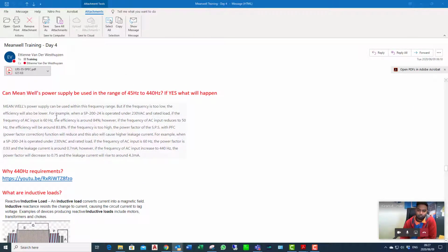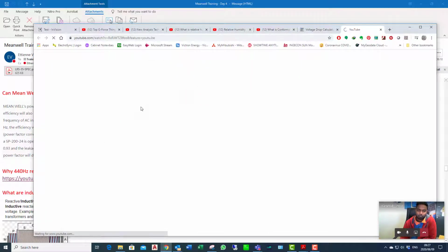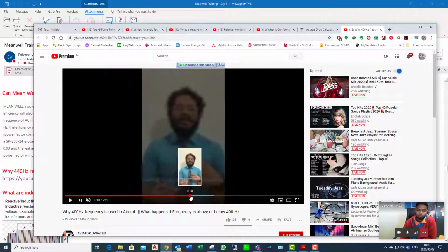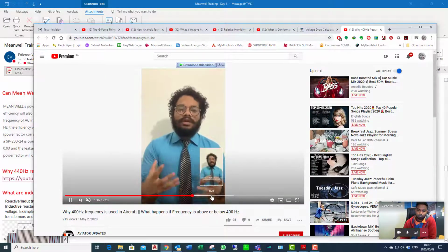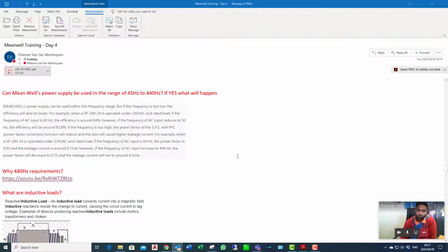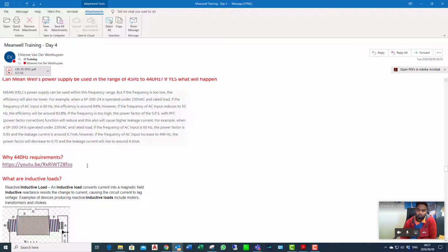And why do they do it? It's because of aircraft. If you look there, there's a short video where they've spoken about it. Because you've got the higher frequency, if you listen to this video of this guy, maybe a bit boring, it'll explain to you that your transformer and everything shrinks if you start running at 400 hertz. So there are very specific power supplies out there. I usually stay away from it because there are no warranties that you can offer, although it will work. And it's up to the client to make that decision.